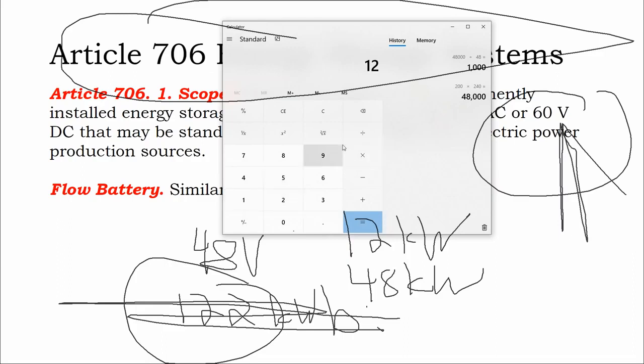What's more typical is a home having maybe 12 kilowatts as a backup solar inverter, but even then you're using 250, 300 amp cable and getting up into 4-aught, which is like the thickest welder cable you've seen. And once you're beyond 4-aught, that gets you into utility scale cable.